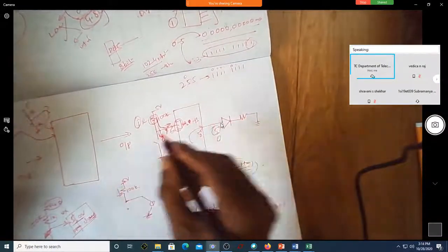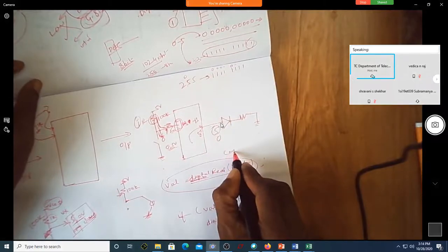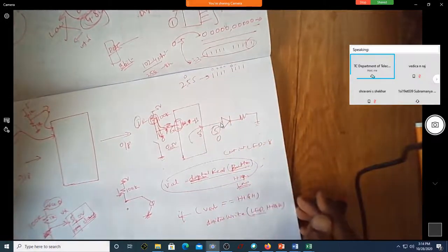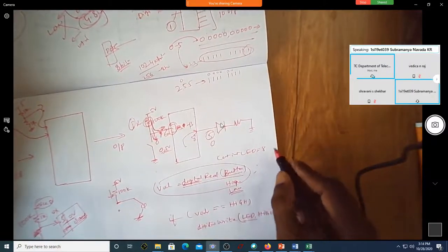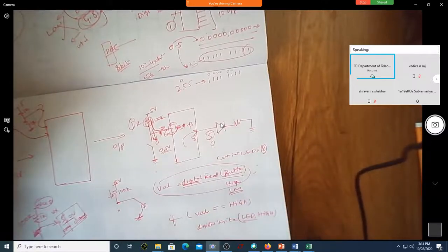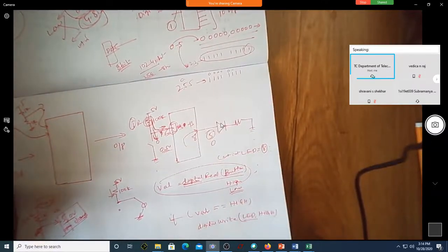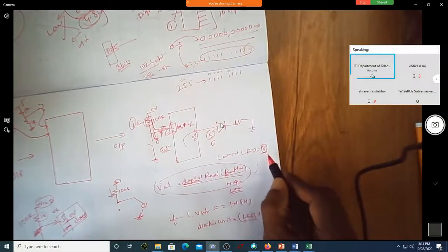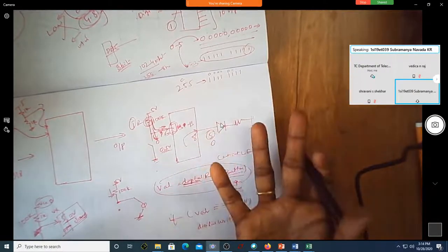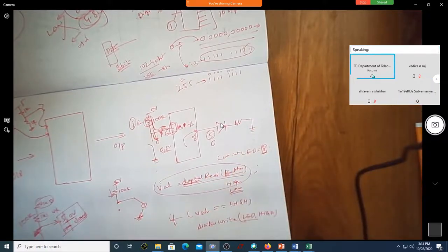See, what is this LED? Maybe in the beginning you would have written constant integer LED is 8. So this is assigning pin number 8 as LED. And what is this 8 now? It is an output pin. So in the pin mode, I have to say pin mode LED is output.